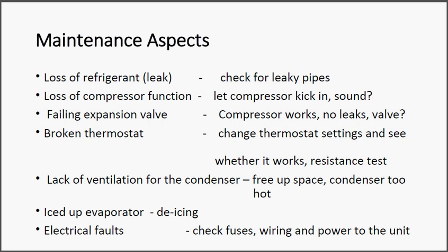And then the last one, which I mentioned to start off with, is electrical faults. Just check whether the fuses are okay, whether there's power getting to the refrigeration unit. Make sure that the wiring is okay. Make sure that there's power to the unit. Make sure that fuses inside the unit haven't blown. And then also make sure that you get power everywhere where you should get it. Obviously, it's got to be done by a certified electrician or somebody that's authorized to do it. But that's normally the checks you will be doing with this.